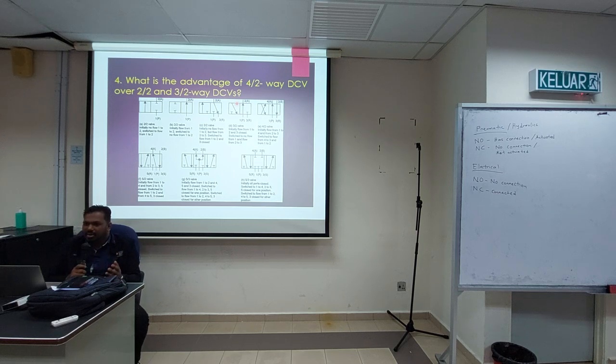Okay, in terms of number of port or number of position. So you just beli satu alat, okay, or one component, but you can use it to do multiple work at the same time. So that's the function lah. That's the advantage. Okay, so 4/2 dia ada more port. Okay, 4/2. Kalau 4/3 dia ada more port and also more position.